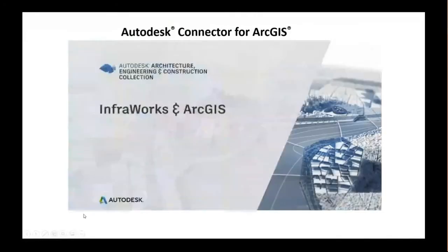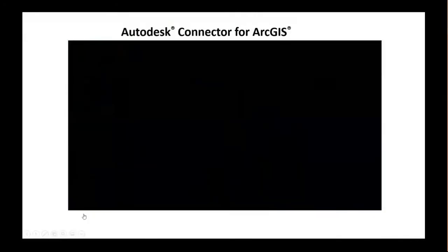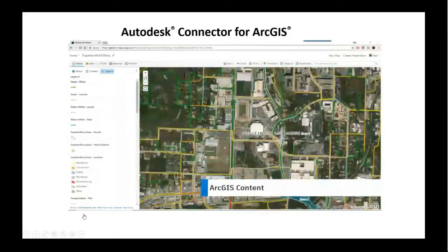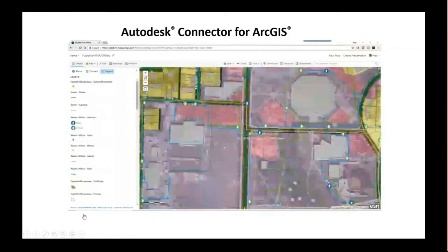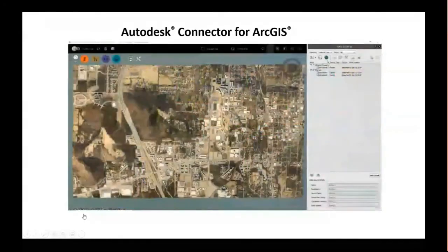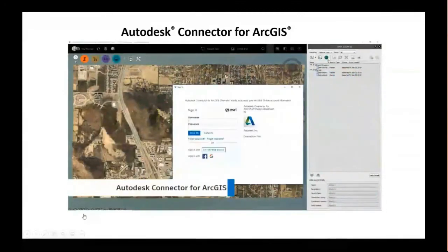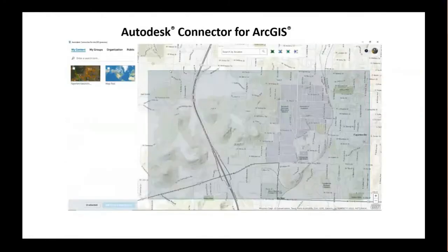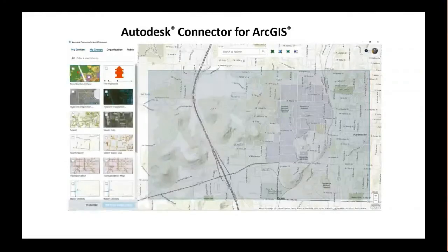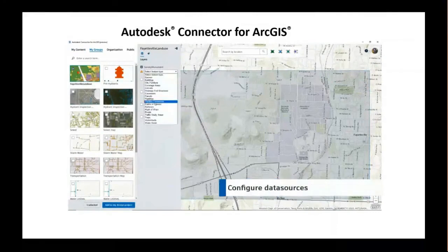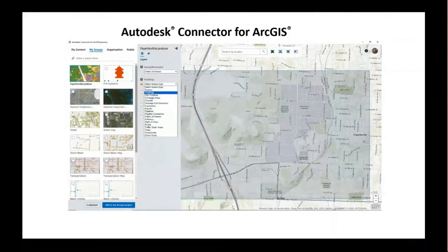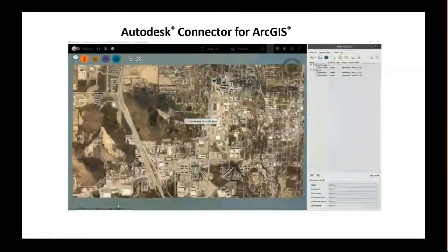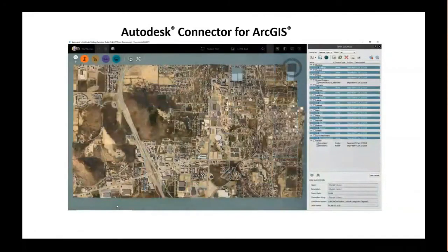In 2019, Autodesk released this functionality. This is new functionality in 2019.2, InfraWorks and Civil 3D, where you have the ability to connect right into GIS information published to ArcGIS. So this enables BIM workflows on the front end of project design, letting customers build from Civil 3D and InfraWorks directly into the GIS model.